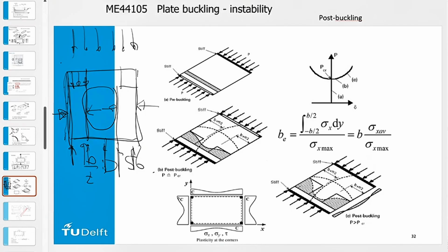And then you get, in reality, if you do that into a calculation, you assume that the edges go up to the yield. In the middle, we don't have any load, and then in the edges, it is supported again. And this is what we call the width, the maximum width between the plates where the yield and the buckling limits are the same. So that is the effective width.